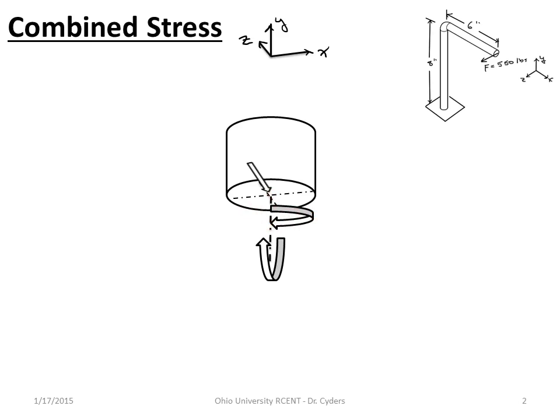And then I've got a reaction bending moment here because this is rigidly mounted, and that is about x, and according to the right-hand rule is going to be a negative bending moment reaction there. And so these three things are each going to independently cause stresses, and then we're going to pick points on this cross-section in terms of where those things are maximum.